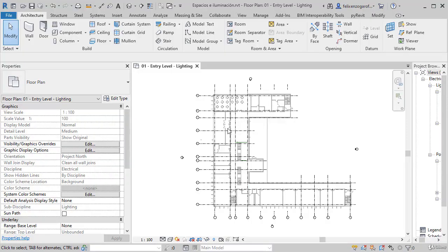Usually, when we create a design in architecture, not talking about electrical engineering, we use a tool called Rooms, located under the Architecture tab. It identifies what will be the use of each zone of our building. It may be a cafeteria, a conference room, etc. However, when we use Revit tools for analysis, specifically electrical engineering, the Rooms tool is not enough to identify these environments.